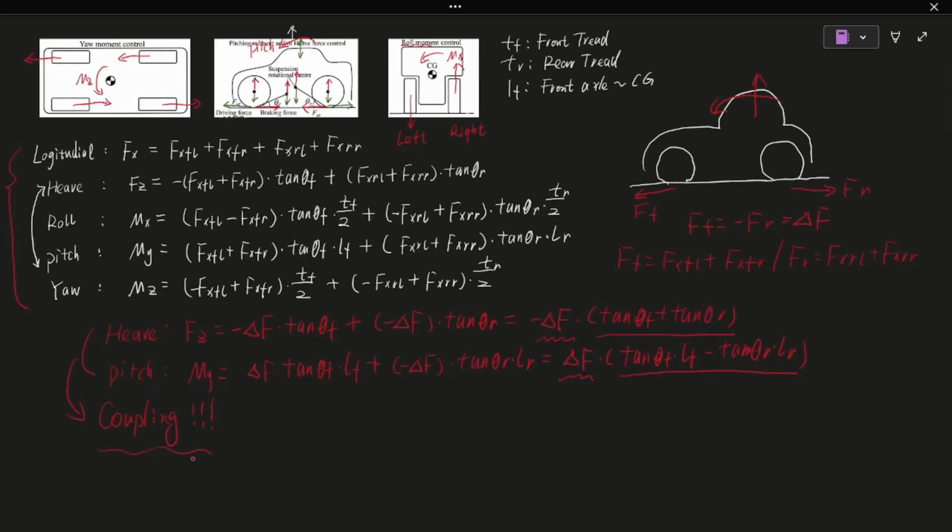In the last episode, we explained how to use in-wheel motors to establish the 5 degree of freedom equations of the vehicle. In this episode, we explain another important innovation in the paper, the decoupling of each motion. Establish the 3 degree of freedom kinematic equations and add the control forces and moments to the equations.